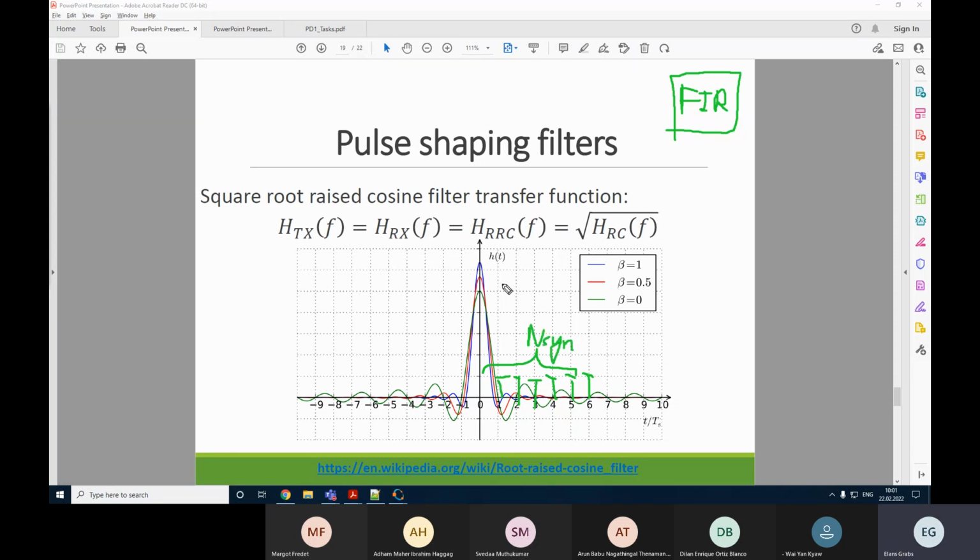So that's exactly it. Number of symbols is accordingly how many neighbor symbols are considered in this impulse response, except for the currently transmitted one. So currently transmitted one is 0, then we have 1, 2, 3, 4, or 5. I don't believe there is more than 5 for anybody of you. So there are only options for 3, 4, or 5 symbols. How much of these side lobe symbols we are going to have? That is this parameter.